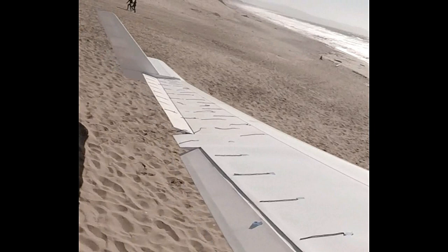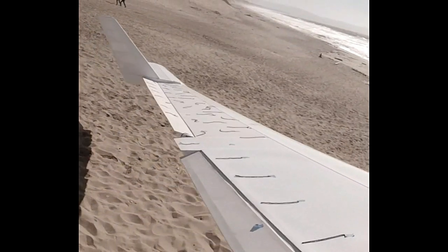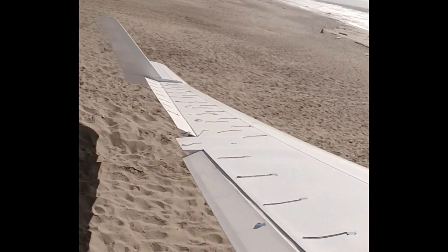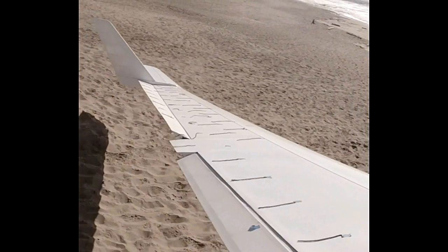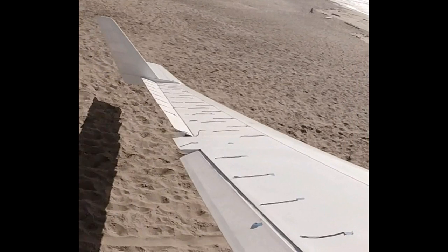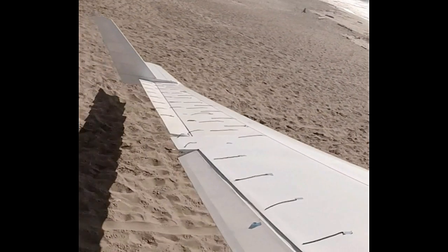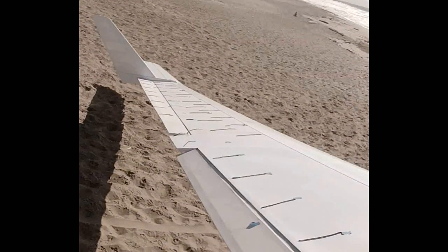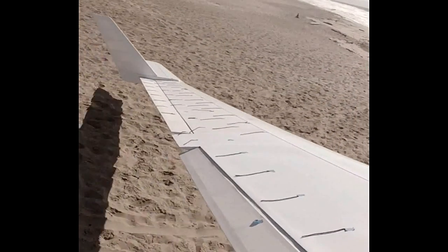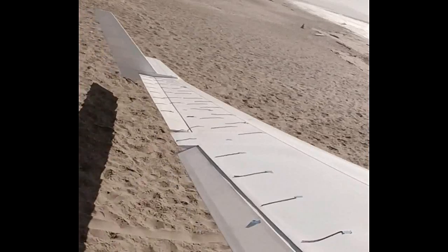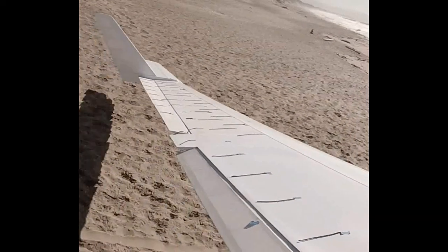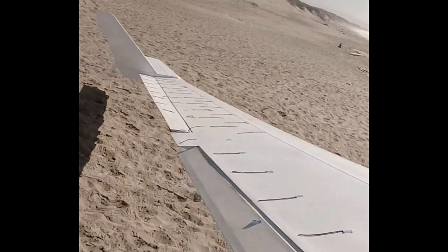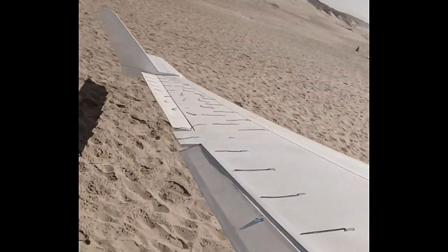Flow looks good with up elevon. My original wing, if I had that much elevon up, it would start some spanwise flow, but the winglet sitting there helps stop that from happening. Flow on the forward portion of the wing looks good, so we're doing fine. I get the wingtip pretty close to the ground here, then I back off that aileron. I really don't want to go in the ocean, so I'm banking as much as I can to get it around the corner so I don't head out over the water.